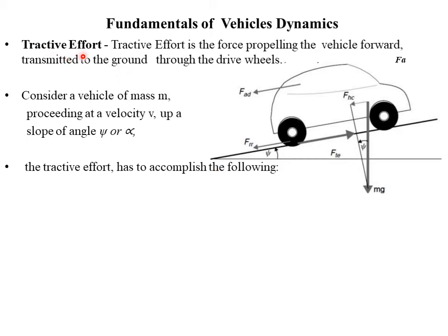So what is this tractive effort or tractive force? This tractive force is a force that a vehicle needs to propel in the forward direction. Why this force is important is that when a vehicle moves in the forward direction, there will be a lot of resistive forces or opposite forces acting on the vehicle.